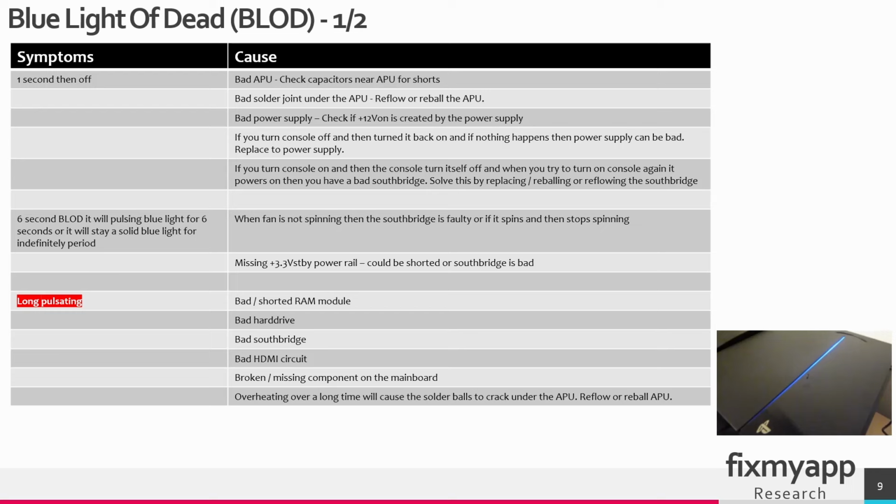Also, one of the causes can be a bad power supply. So you have to check if the 12 volt is created when you press the power button. Next, if you turn the console off and you turn it back on and nothing else happens, then the power supply can be bad. So also check the power supply.